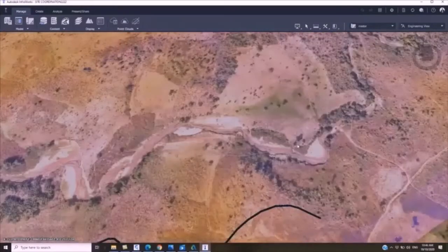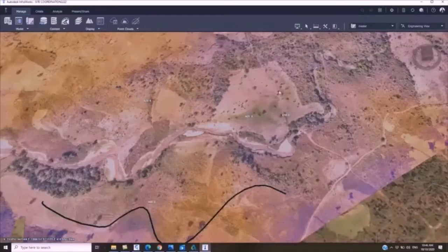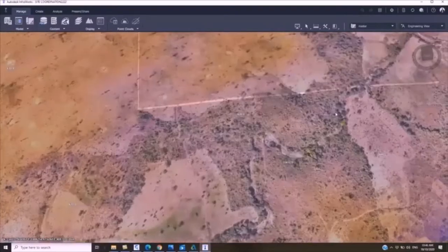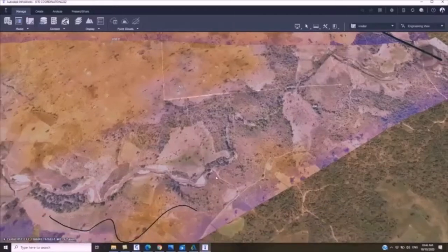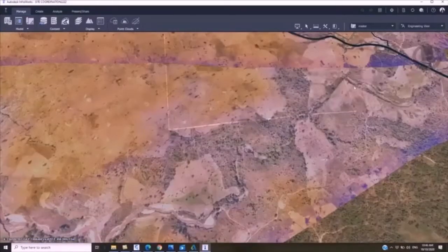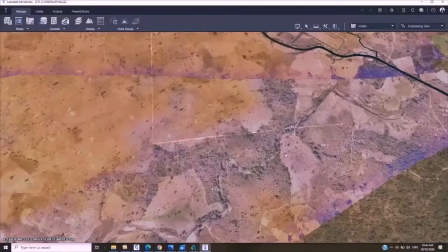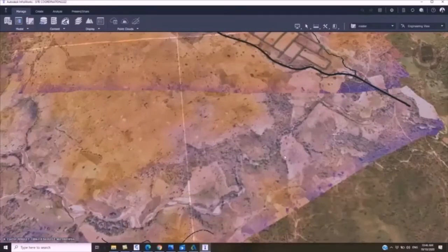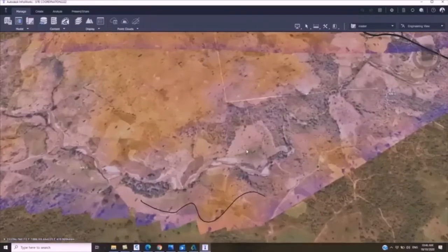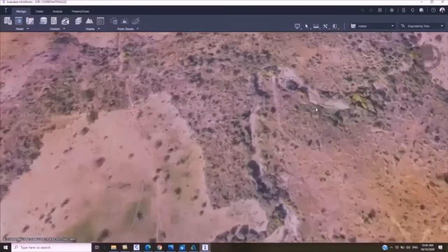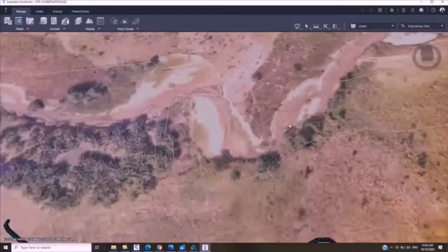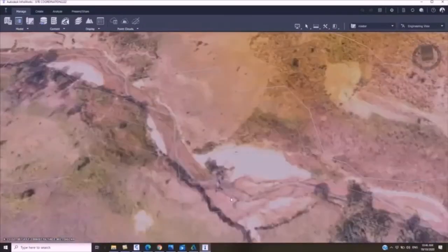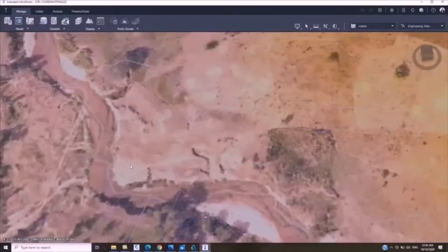Assuming it was captured during the rainy season, definitely the InfraWorks model builder will show us the river flow line and tributaries as information that will guide our design of our storm water connections. But because this capture for the model builder was done during the dry season, and the drone flight was also carried out during the dry season, you can only see that the tributary line has been updated, but you cannot see water flowing, just the pattern of the external water shown in the map.